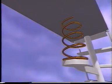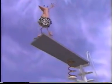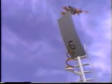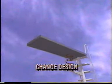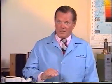Increasing the section of a spring, for instance, makes a stiffer spring and changes its spring rate. Beefing it up can also lead to space, weight, and clearance problems. Sometimes it may be feasible to change the design of a part, adding flanges or corrugations or braces to make it stronger and reduce the stress. Again, this increases the stiffness, which may be acceptable in some cases, but not in others. We can also avoid yielding by reducing the load on the part. Once again, this may not be feasible.